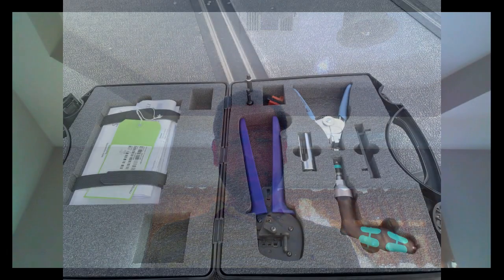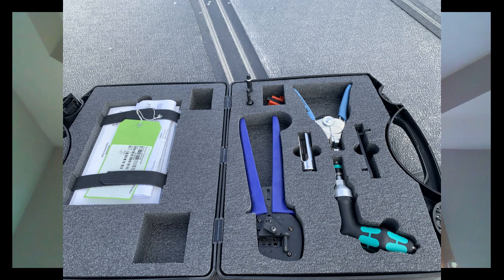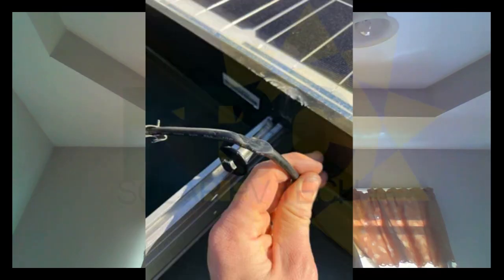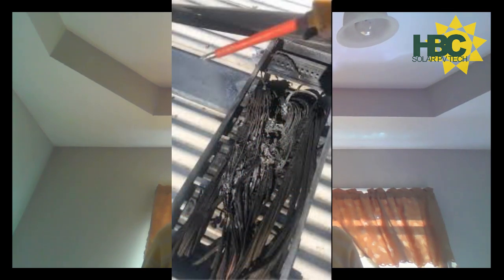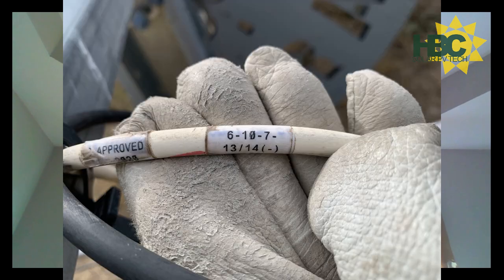How to repair ground faults in PV systems. Once you've found the ground fault, you have several options for repairing it. If the damaged conductor is in conduit or free air, you can replace it with a new undamaged conductor. A single conductor in a conduit with other conductors may be challenging to replace without removing all conductors from the conduit.